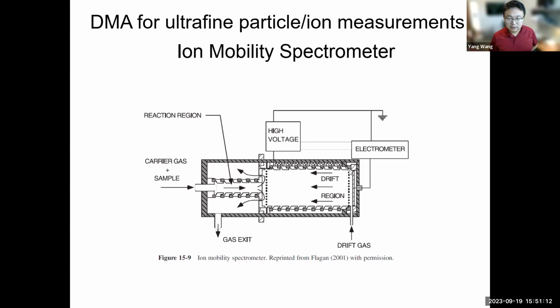So there is an electric field that accelerates the aerosols, right? For each ring here, they use a different voltage. So you accelerate the aerosols, and then eventually they reach the outlet, and they're detected by the electrometer. So for this drift tube, you introduce the aerosols as pulses. You introduce a pulse of the aerosol flow that contains larger particles and smaller particles, but then the time for the particles to eventually reach the electrometer, right? That's related to